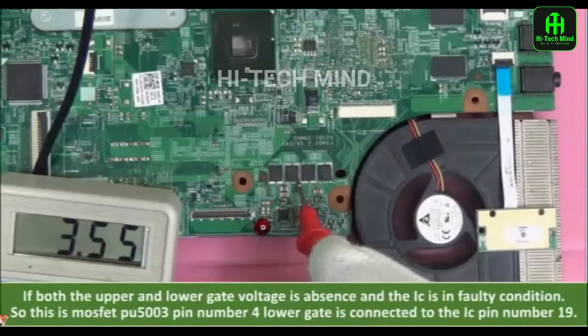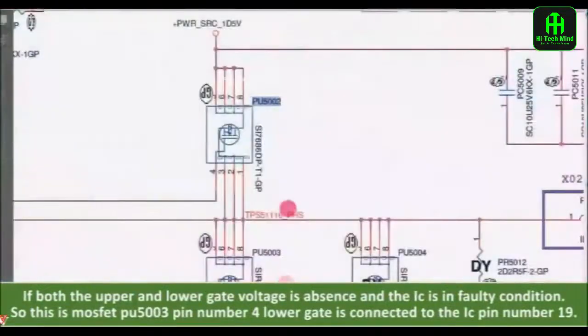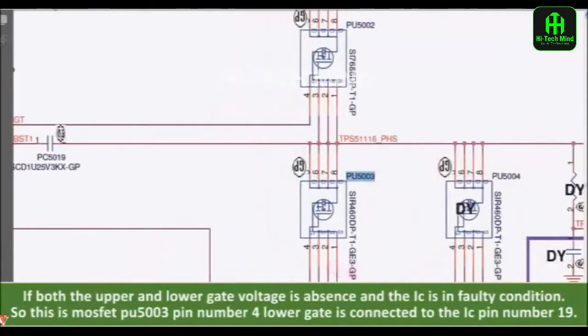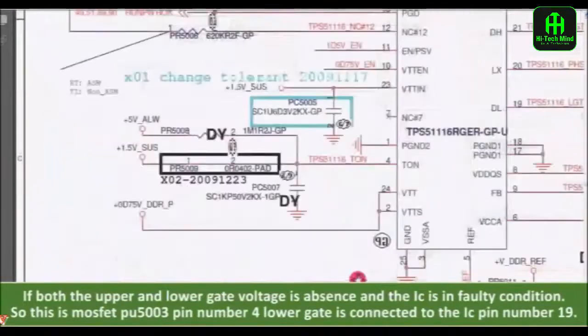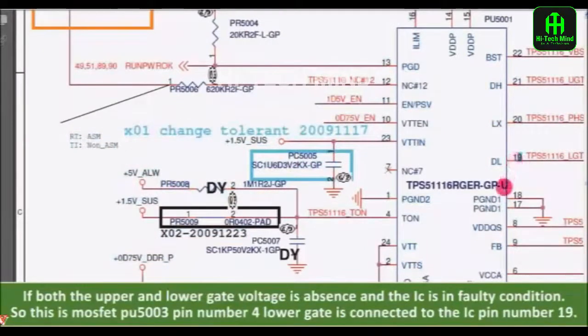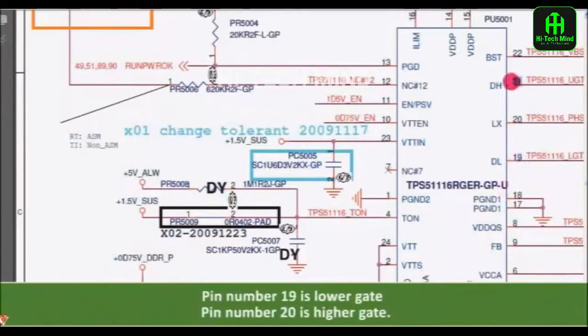If both the upper and lower gate voltages are absent, the IC is in faulty condition. So this is MOSFET PU 5003 pin number 4. This pin number 4 is mentioned as lower gate and it is connected to IC pin number 19. Pin number 19 is the lower gate.